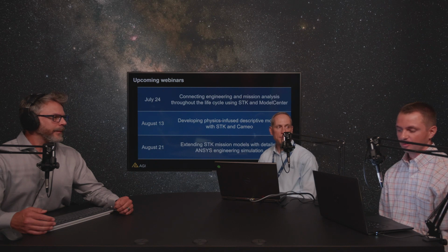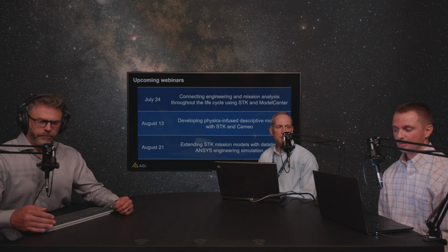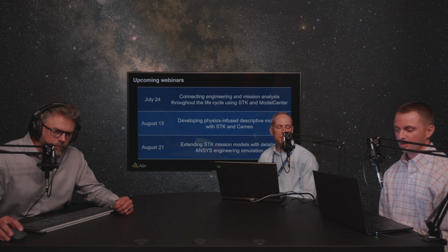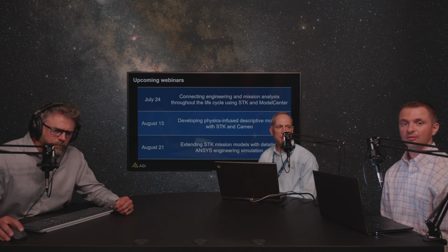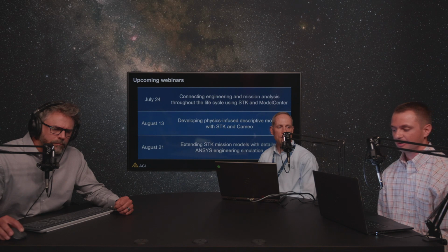And so what we did was we ran a simulation in Solus, and for a CubeSat mission in orbit, we looked at the eclipse times and things of that nature, and then we exported a report in CSV format that had time and Earth albedo and solar flux. And then sent that over to the Ansys engineers. They were able to load that right into Ansys Mechanical and to do the detailed thermal FEA analysis. So that was how that was done in a little bit more detail. But in general, it was that file input-output share.